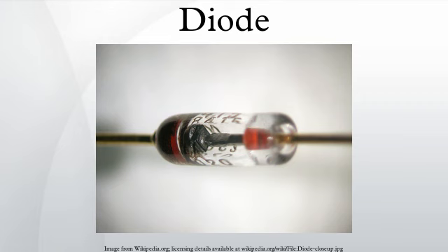Avalanche diodes are designed to break down at a well-defined reverse voltage without being destroyed. The difference between the avalanche diode and the Zener is that the channel length of the former exceeds the mean free path of the electrons, so there are collisions between them on the way out. The only practical difference is that the 2 types have temperature coefficients of opposite polarities.